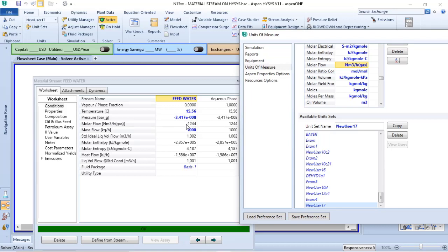So in this case, Aspen HYSYS is considering that this amount of water, although it is in liquid phase, is now in gas phase. Verify that for normal conditions, 0 Celsius degree and 1 atm, water will not be a gas. But in any case, Aspen HYSYS is using the convention of 22.455 cubic meters per kilogram mole of the component to do the calculation.